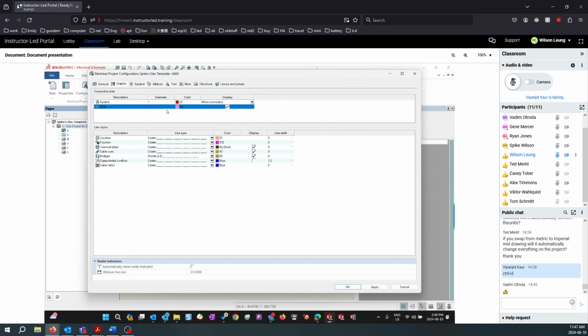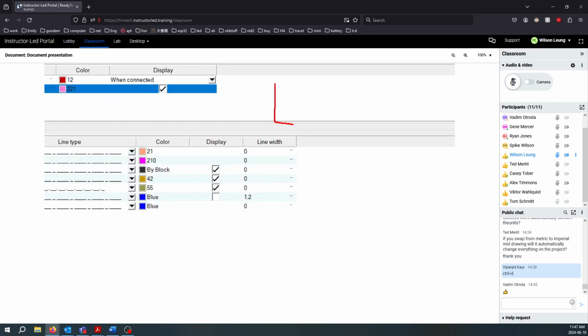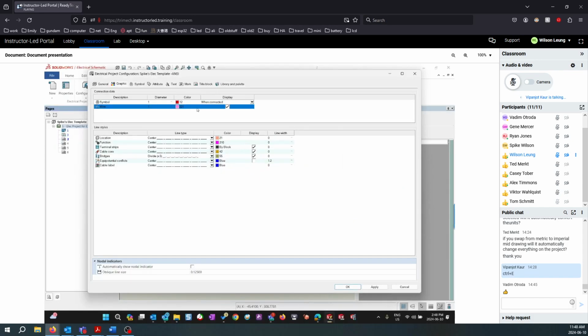Next one is wire connection dot. If I've got a fuse component here, and then I have another wire connecting from here to here. So when multiple wires are connected like this, we would see a connection dot here, but in pink color. So for a directly connected wire, if it's the same type of wire linked, we would see a pink connection dot from wire to wire.